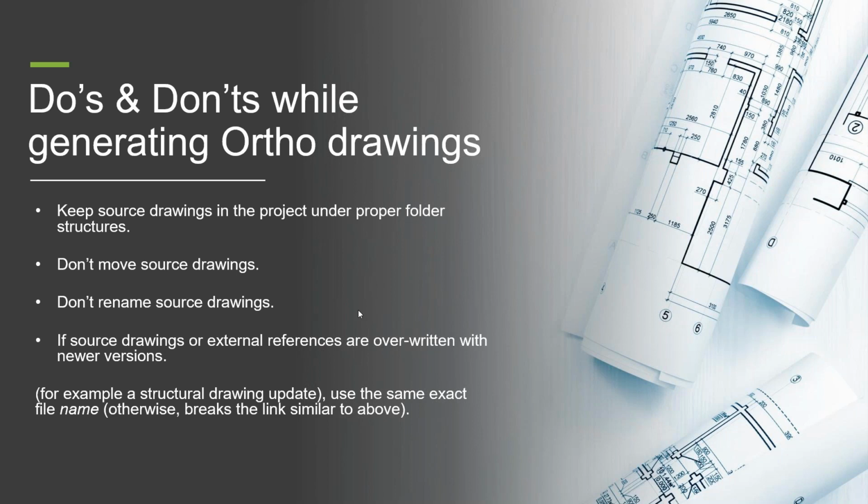So yeah, as far as the connections go, this is sort of the same concept with deleting stuff out of your specs. If you do that, you lose the IDs that are stored that connect the specs to the catalogs and that connect the specs to the models. So if you want to keep connection in Plant 3D, you're better off modifying rather than removing stuff. And in this case, don't remove models from your 3D project if those models are referenced in orthos, unless you're ready to create those ortho views.